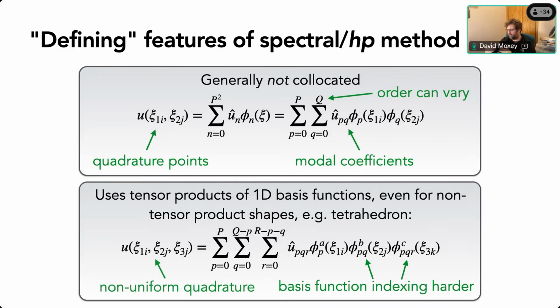So what we tend to do is to use a non-uniform quadrature. For a triangle, for example, we might select a standard Gauss-Lobatto quadrature for the direction that's not being collapsed. And then for the direction that is collapsed, we'd use something like a Gauss-Radau quadrature, where you're excluding the endpoint that corresponds to your singularity, where you've collapsed the shape down.